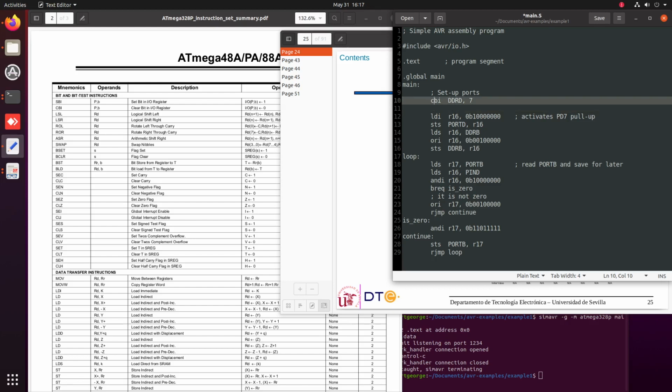It's just subtracting this number, number 20. We can do it manually, but the preprocessor already has a function to do that. The name of the function is a bit clumsy because it's SFR IO ADDR. So this is a preprocessor function, let's say, that will take the address of any peripheral and convert that memory address to input-output address. So whenever we want to access a peripheral through the input-output bus and not through the memory bus, we need to prepend this macro function. It's a bit big, but this is the way it's defined in the AVR library. So this will be the way to do it.